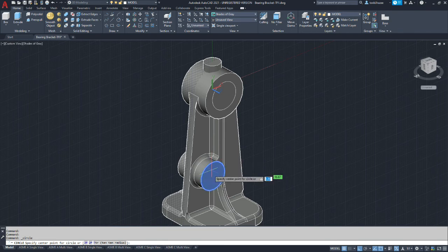And you hover over the edge, you should see the circle, and you should see the center point show up, and then you can select it. Sometimes zooming in and out helps with that aspect. Okay, and our second one is a 13 millimeter hole. It's a plain hole drilled through. So we're going to change to a diameter again, and it's going to be 13. Alright.